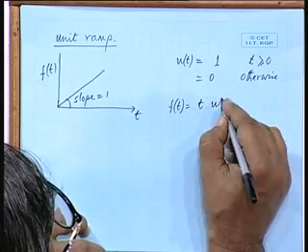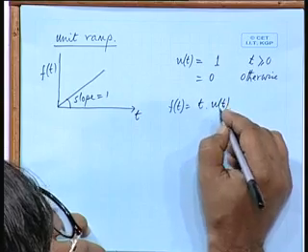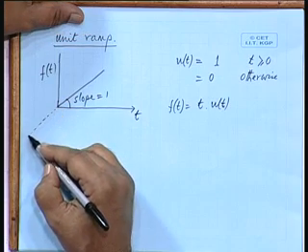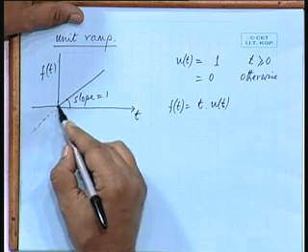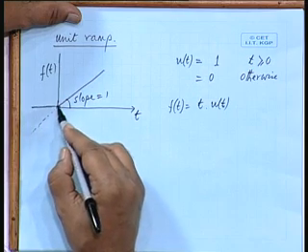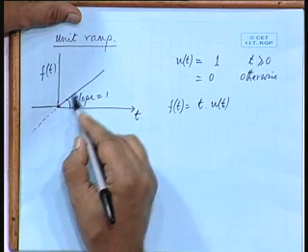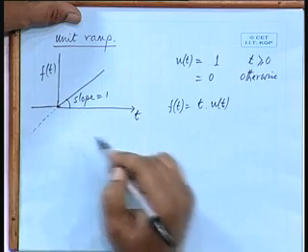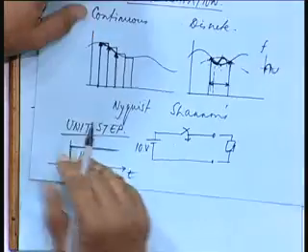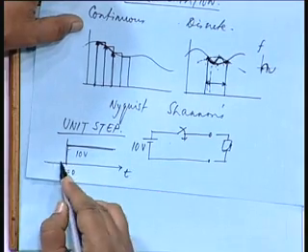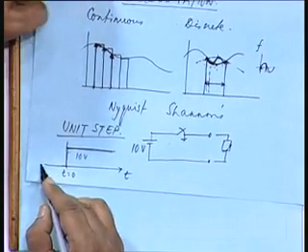into u(t). Why into u(t)? The function t is also having values in the negative region of time, but I want a function which will start from t equal to 0, all right. Before that it is non-existent. So, if I multiply this by a unit step of this type, then on the left hand side you get 0.